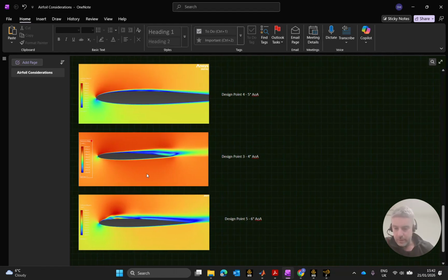When we look at the pressure distributions, there's no real continuity between 3 coming on to 4 coming on to 5. If anyone says, well, what angle of attack do you want to run your airfoil at, I'd say here, let's go 5 degrees. But if we waited, as I said, a split second later, we probably would have seen this bubble would have developed an awful lot more into something like we're seeing here. This region here is obviously lifting, and it's lifted at a very early stage because we see it there. It's just come back down again and maybe reattached at that section. But yeah, so that's it.